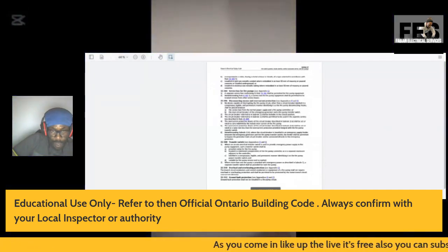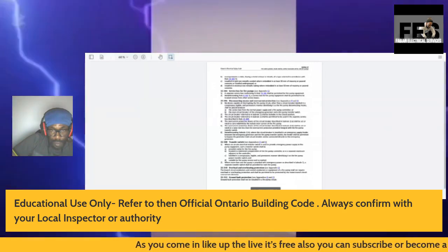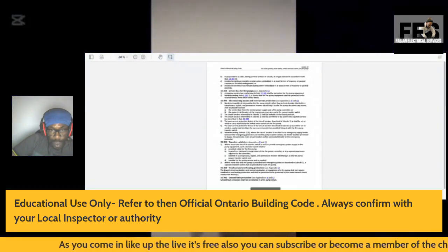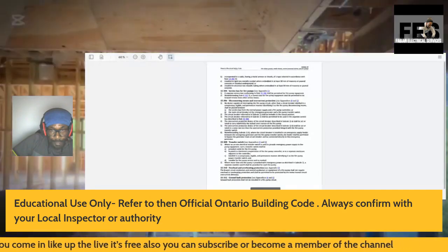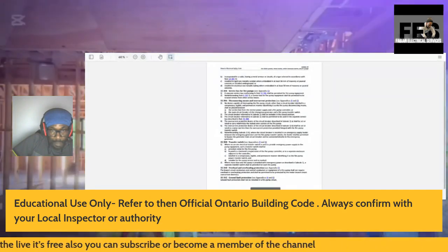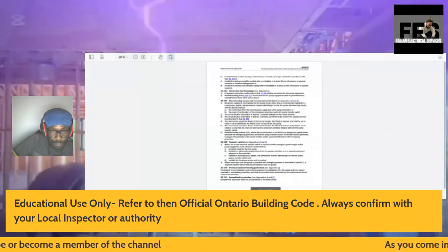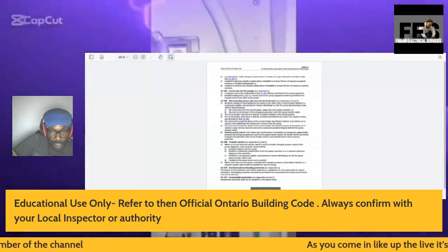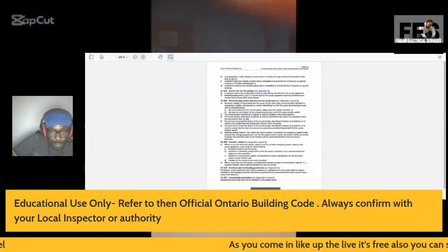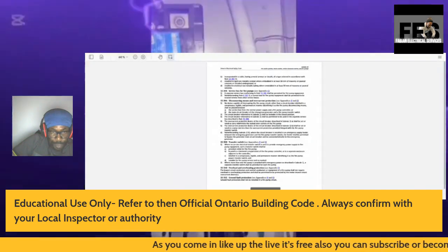The overcurrent protective device of the circuit breaker described in Subrule 1A shall be set or rated to carry indefinitely the locked rotor current of the fire pumps.